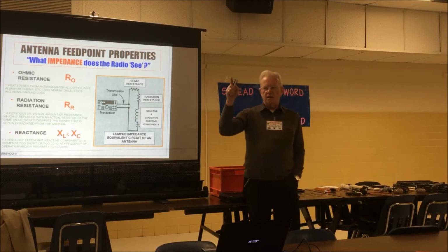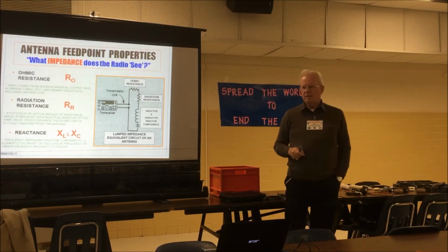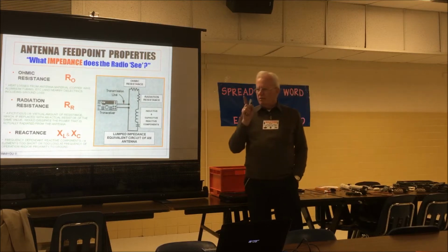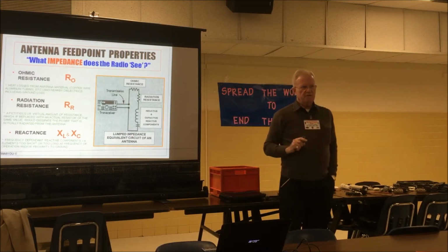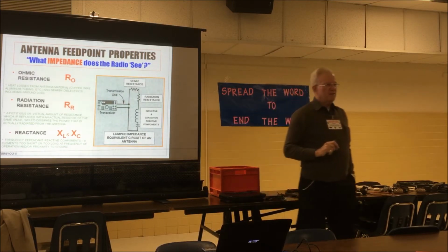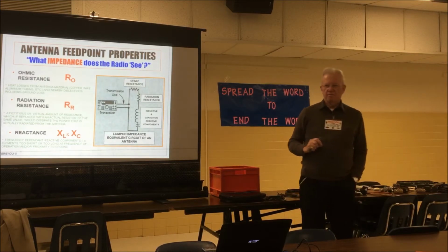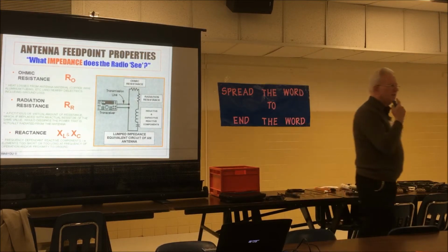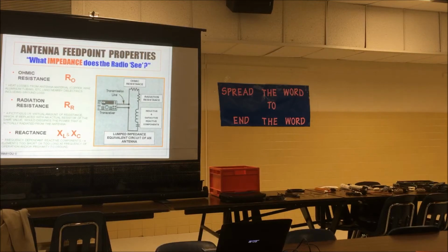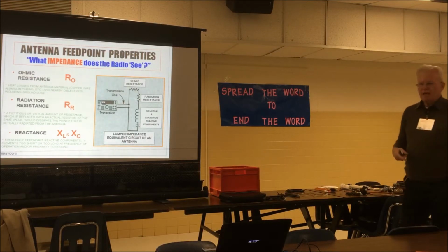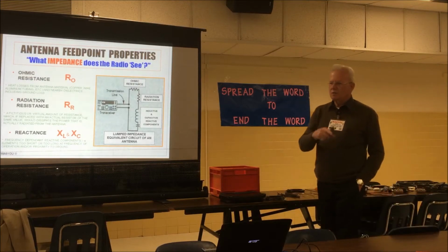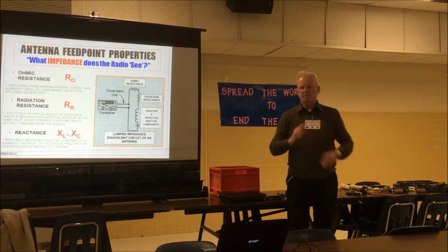It looks like an RL circuit. And the radio looks out and sees some resistance in series with some inductance. So what do you think your tuner does, guys? What do you think your tuner does? Your tuner adds some capacitance to create some capacitive reactance to, again, cancel it out.